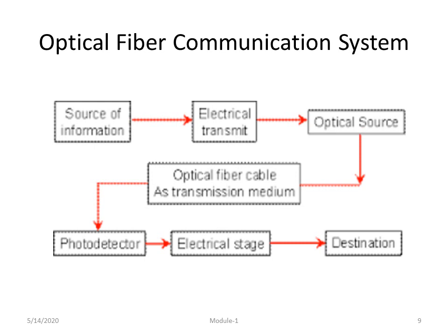So what is this? Already you know what a communication system is. A general communication system should consist of a transmitter, a receiver, and between them a channel. Here in optical fiber communication, transmitter and receiver should be there, but the channel itself is the optical fiber cable. The source of information may be an analog or a digital signal, but the main thing we need to include in the transmitter and receiver is that whatever information is transmitted through the optical fiber is in the form of a light signal.